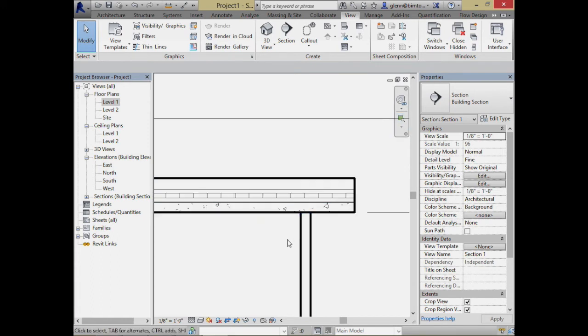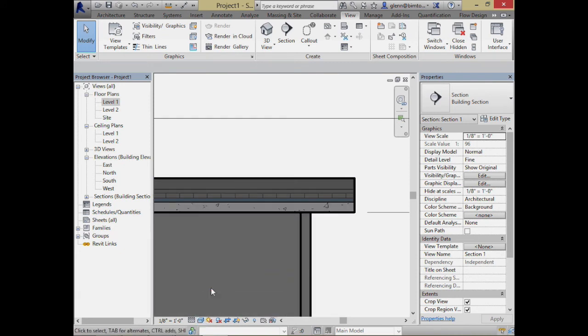So this will point out something about green roofs that you have to stop to consider, and that is as follows. I've got all my different layers, they're looking pretty good. I've got my concrete, my airspace, my insulation, some sand, some sort of material, that's all looking good. Things you have to consider with green roofs are kind of the end condition.